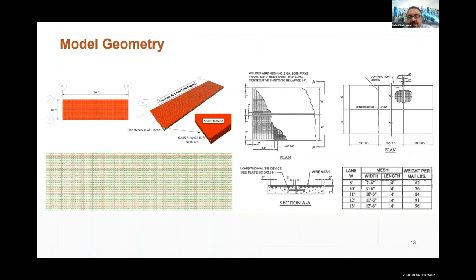The finite element model consists of 2,125 nodes and 2,016 shell elements. We evaluate the shear forces and also the maximum bending forces. The bending forces are defined as a local axis moment, which is explained as M11 and M22. M11 and M22 were used as negative and positive moments in the longitudinal and transverse axes.